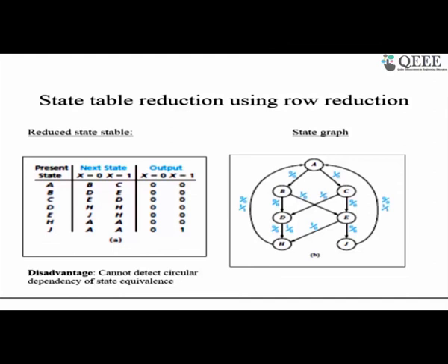We don't want to wait for all 4 bits of BCD to be available for the conversion to begin. If you do so, we have to collect all 4 bits, wait for the conversion and then produce the output. During that time the next set of 4 bits may come. We don't want a delay. So bit by bit, as and when the input comes, we need to produce the output. That may be a reason why serial input, serial output devices are better.